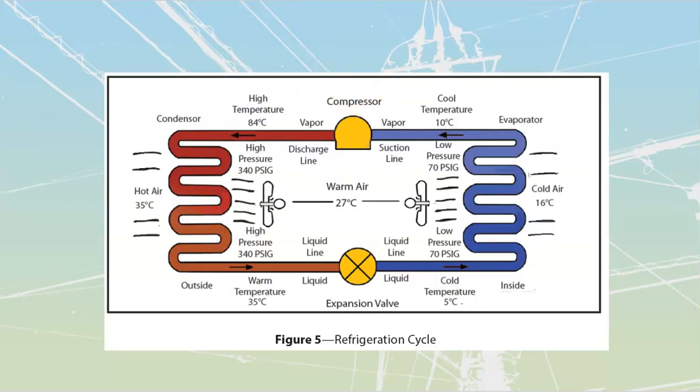You will have two main components there. We're going to have the compressor, which is going to build pressure. We are then going to have the expansion valve over here, which is simply a restriction in the line. There's no great amount of magic to it. All it is, is the pipe that's coming through to there, and then there's just a tiny little hole, they refer to this thing as the orifice, where we are going to press all of our high pressure on this side through onto that side. And because it's only a tiny little hole, it's going to drop to a low pressure on the other side over here.